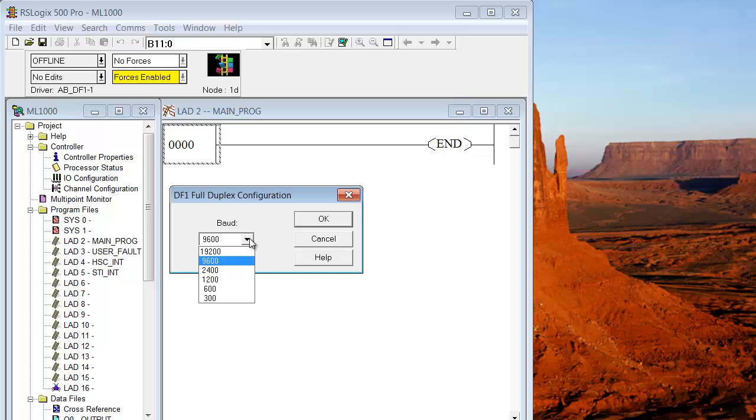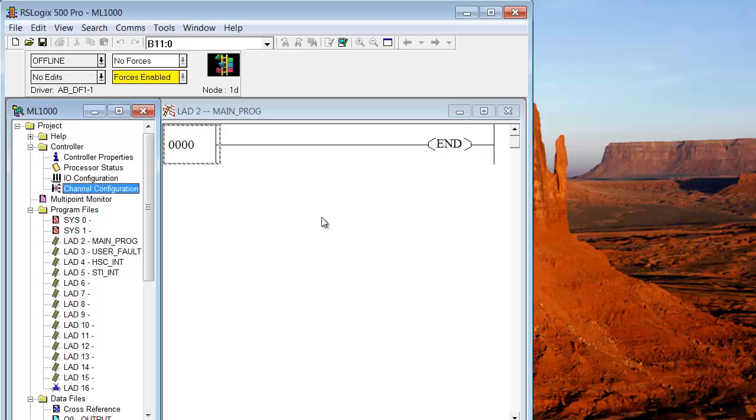So it would read each character twice. And so if you said hello Bob, you would get HHEELLLLOO space BBOOBB, because the 19.2 baud rate, it is assuming that you're sending at the same baud rate. That's enough for that. So there's not much to pick from here. It comes at 9600. You should pick 19.2, but you don't have to do it right here. The reason, well, we'll explain that in a minute. We'll just leave it 9600 because it's okay to start there.